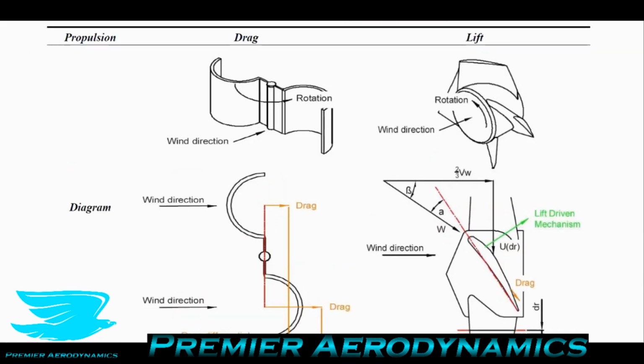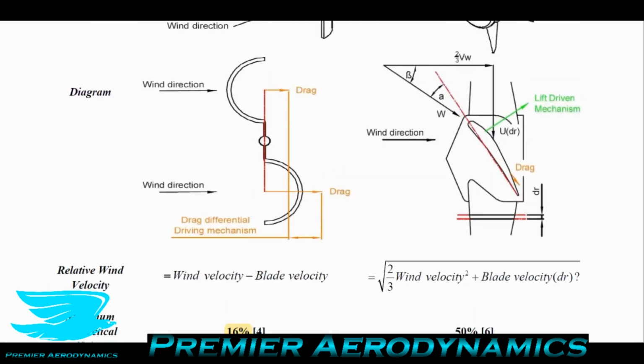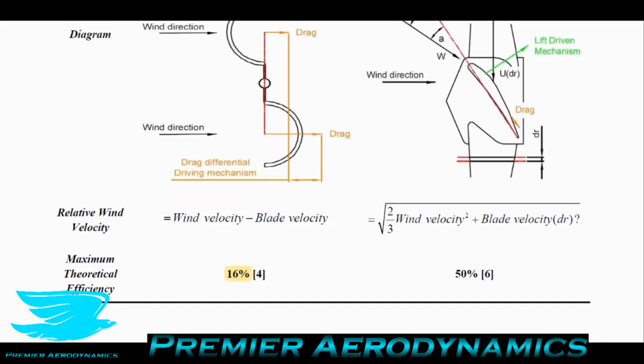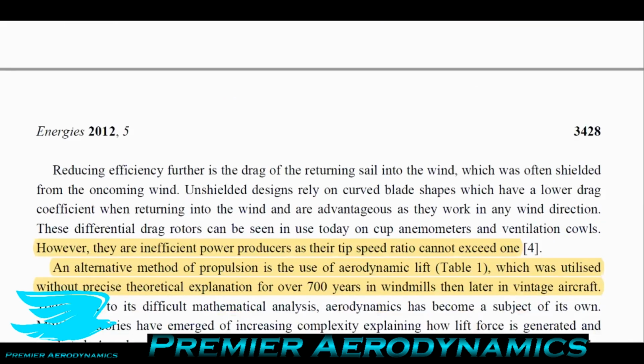Alternatively, wind turbines that use lift to produce the rotational force are not limited by that factor. Interestingly, the maximum theoretical efficiency of a wind turbine that uses drag is only 16%. So 1/6 of 100%. Ones that use lift, as I mentioned, Betz theory, generally 50 to 60% is the theoretical upper limit. In practice, it's a little bit lower than that because of losses, but it's far better than using drag. That's why lift wind turbines are a lot more desirable for gaining energy, I should say.